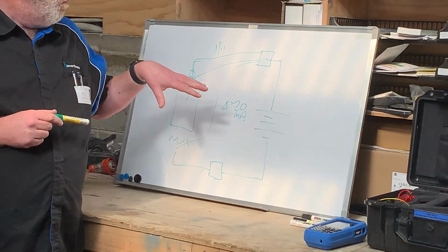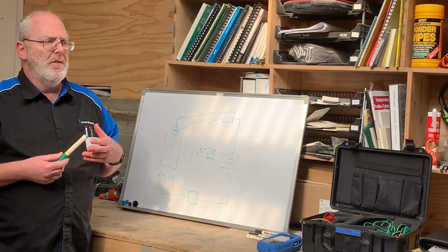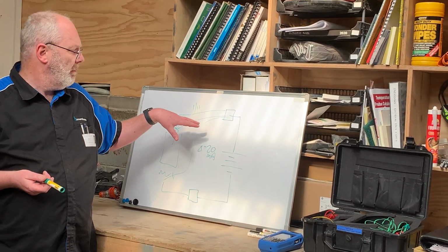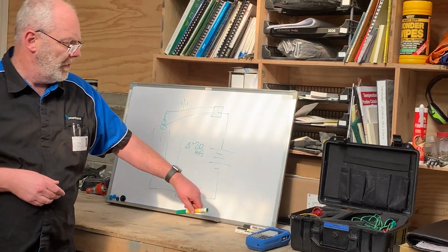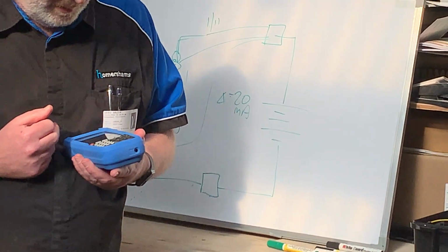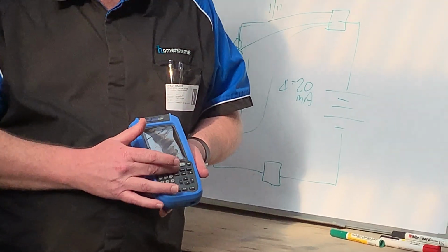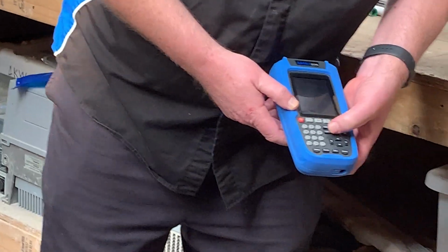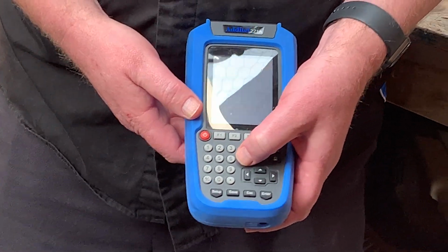So, let's say phase 1, what do we do? Someone's called you up and said, hey Colin, the acid tank is not heating correctly. So it could be any number of things that might have gone skew-whiff. So let's assume for a start that it's the thermocouple. We can simulate that. So on the instrument, we have 2 screens, source and measure. And then each selection of the settings toggles you between source and measure. So for example, if I hit thermocouple RTD, source measure, source measure, source measure. Yeah. So it's quite intuitive.